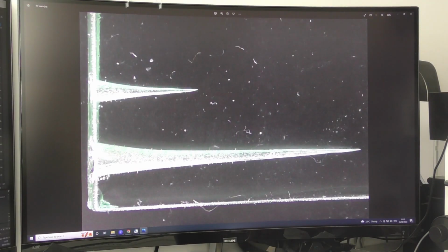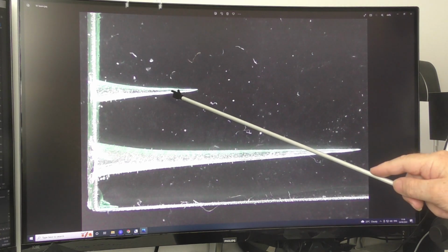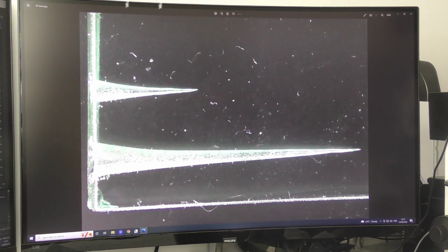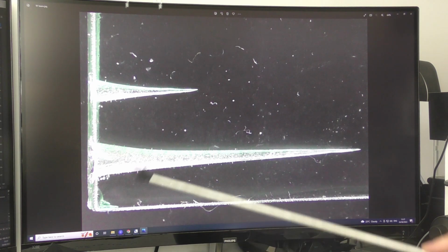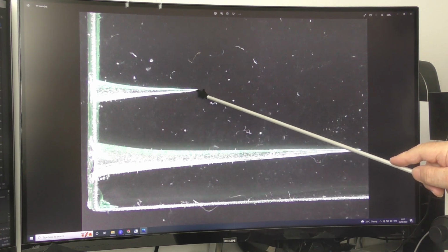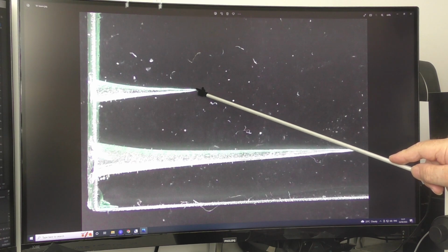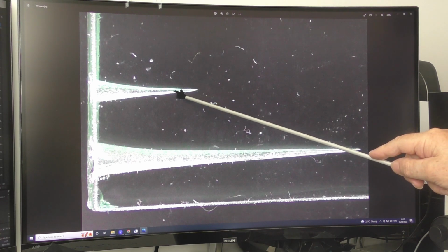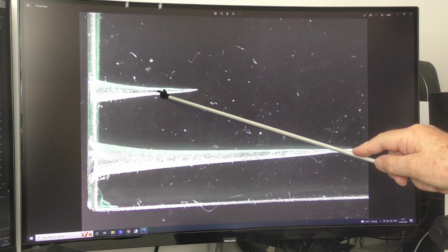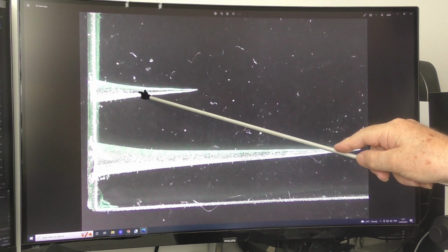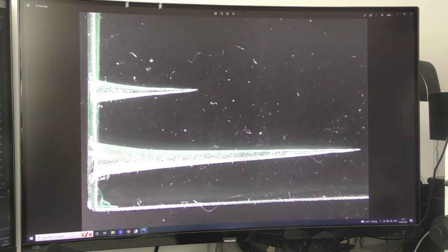I will just remind you of the peculiarity of the RF machine. When the aliasing reaches a point where, as you saw, we get no output power, the problem with an RF tube is the power is always 100%. The thing that's changing is in fact the exposure time of that power. And as that exposure time increases, what happens is the beam size, the dot, is increasing in diameter. So we're not getting a change of power directly, we're getting a change of exposure time, which changes the dot size.